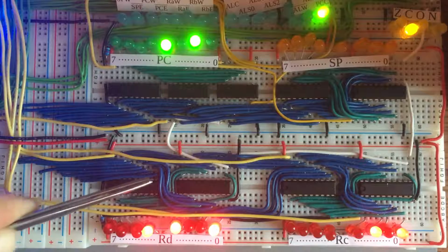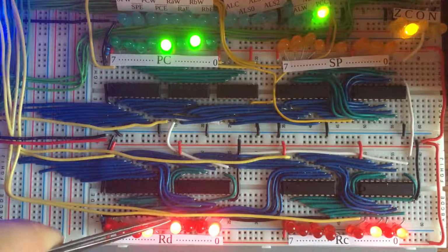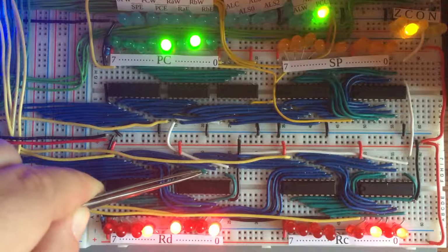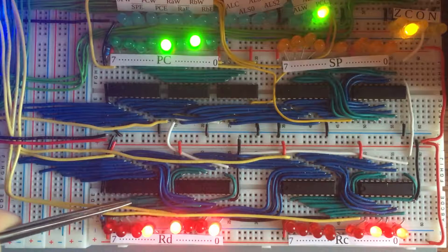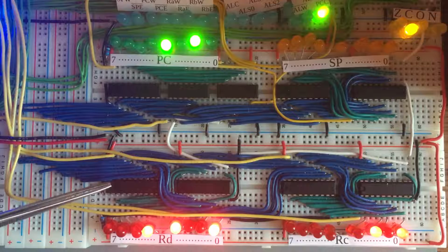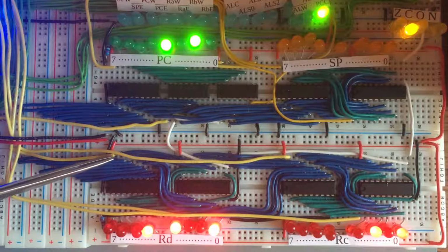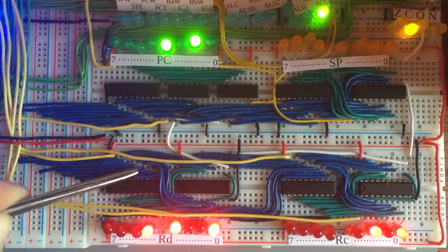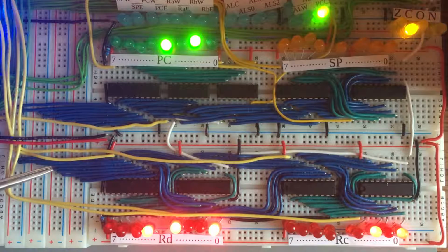We get values coming in from the bus. If we're instructed to do so, they get written inside this register, and they get output immediately onto these green wires. And if at some later point we get an enable D signal, then those green wires are going to pass through this buffer here, this tristate logic, back onto the bus. And that's all the register is, really.